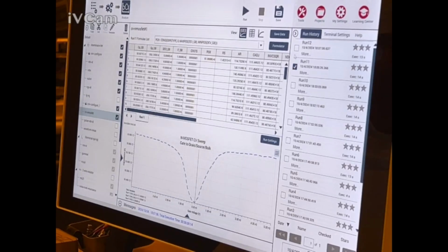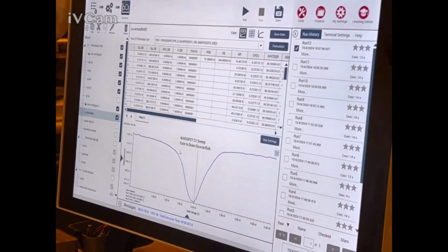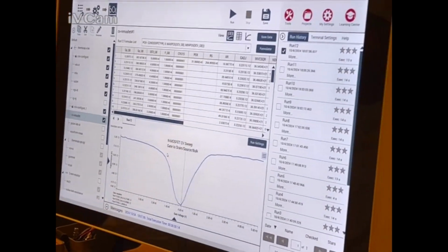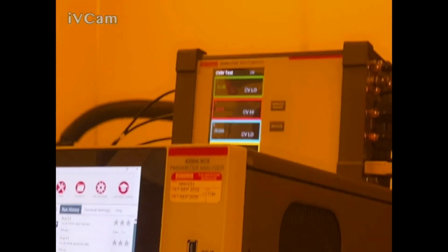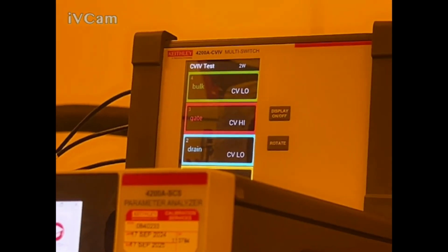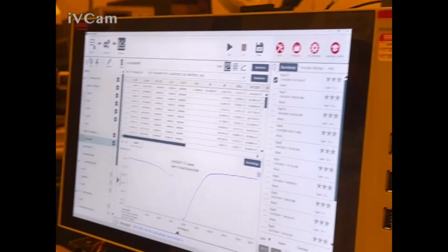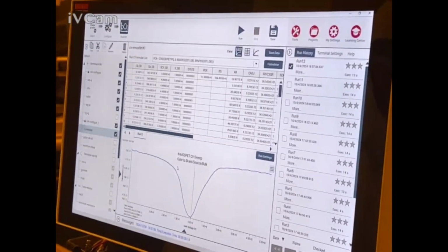55.9 and 5.2. Wow. So there's a lot of capacitance. Most of it's probably coming from this guy, that's my guess. So if you take that out, you can get rid of that capacitance, but the compensation gets rid of it, so you shouldn't have to worry about that.